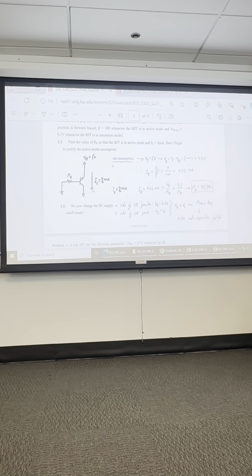Is that okay? No. We're going to go from a negative battery to ground. There's something about that direction that is not working here. But we still proceed until we find a contradiction. That's maybe a contradiction, but it's not really enough. So if we have minus 5 volts on the emitter, what's the voltage on the base? Negative 5.7. Negative 5.7 on the base. But that's the contradiction.